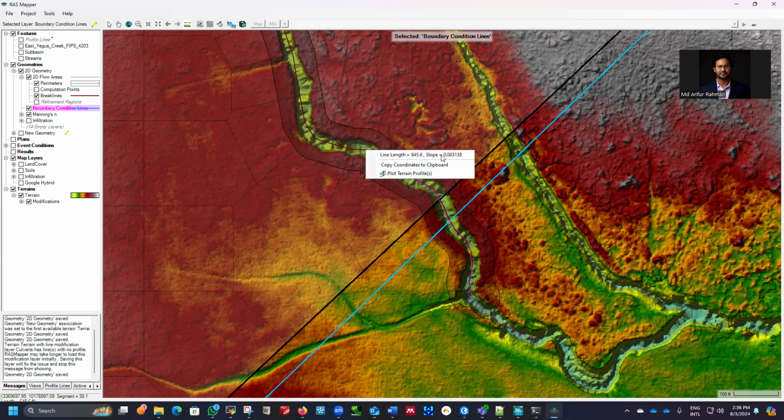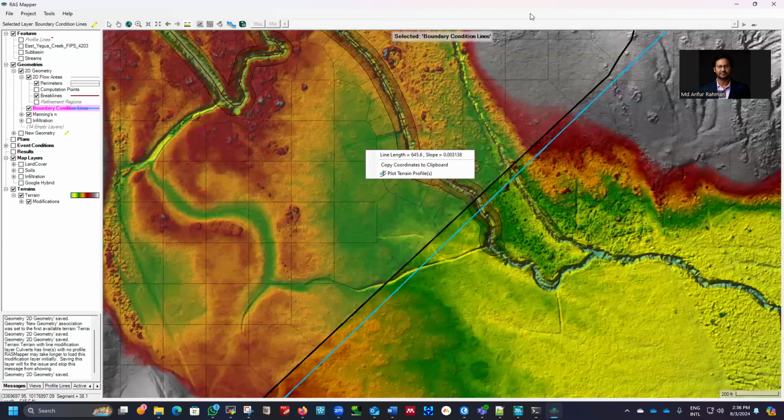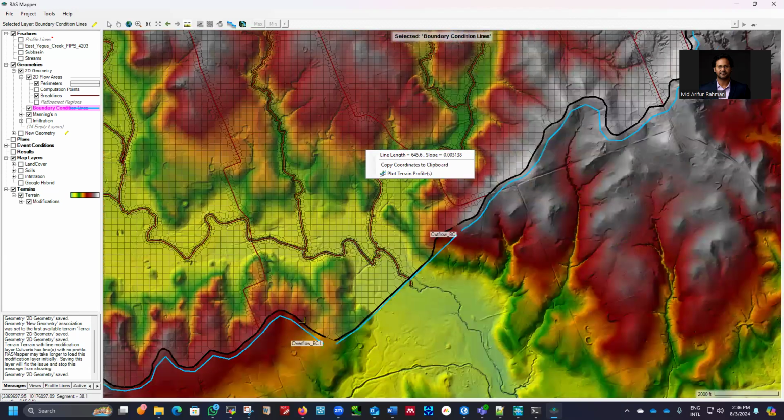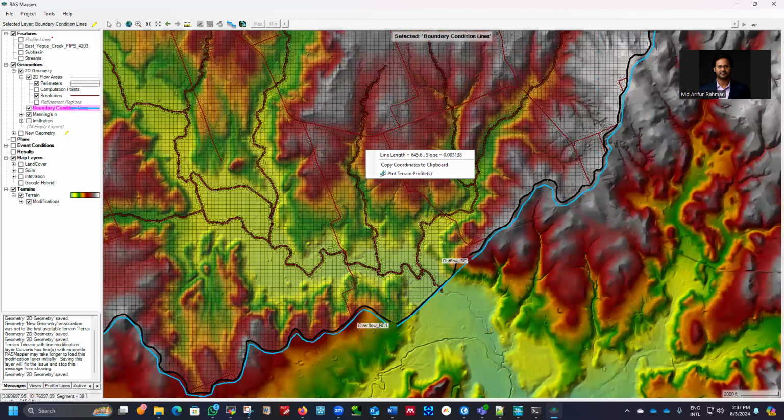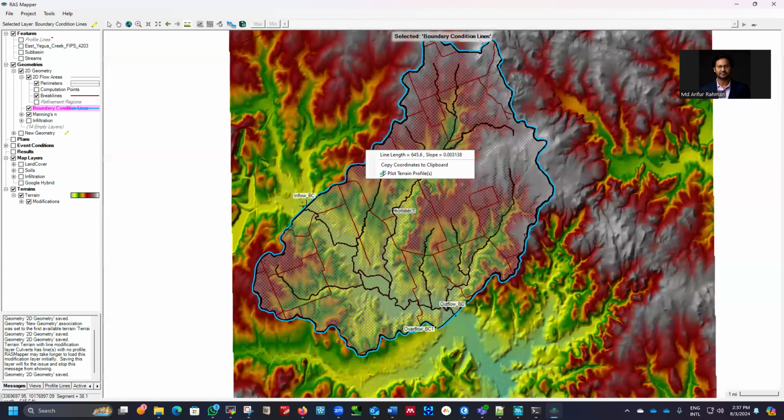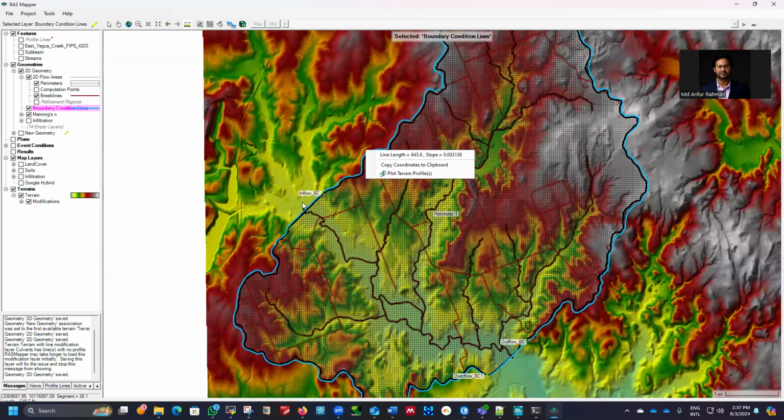So that's the slope, 0.003138. This is the slope we're going to use here as the boundary condition. And for the overflow boundary here, we're just going to use 0.005. So we have different boundary conditions for outflow and for overflow as well. And we need another one here, inflow, but we need to calculate that as a time series.